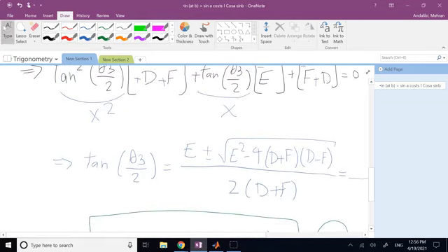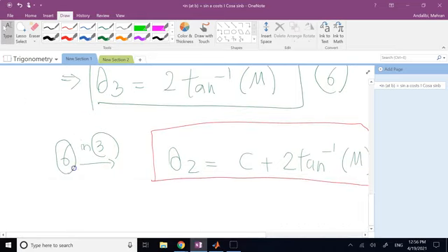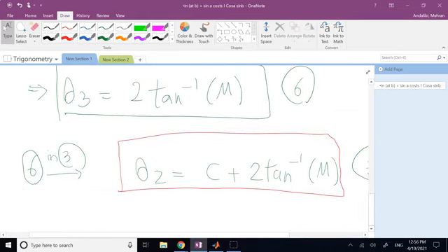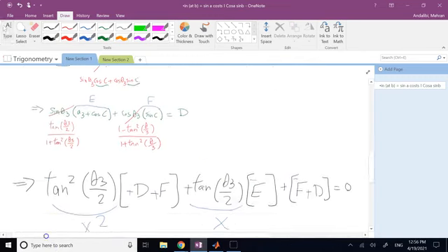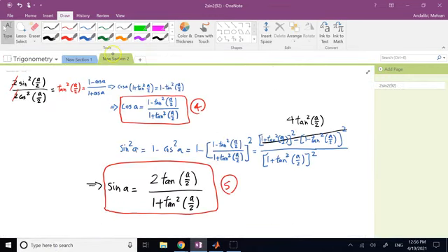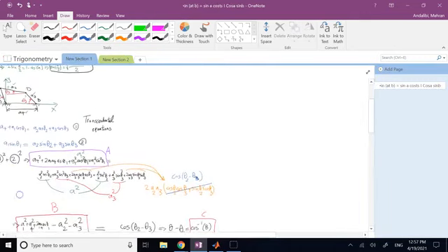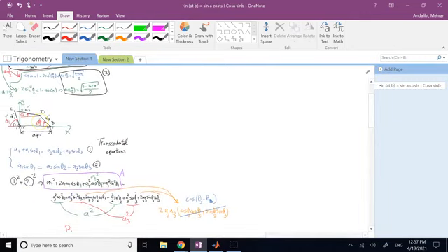So if you go back, you can of course rearrange it all in terms of theta 1 and A1, A2, A3, A4. These are going to be quite chunky big equations, but you see everything is analytical. So now for any theta 1, you can find theta 2 and 3 analytically, thanks to these very important trig equalities or identities.